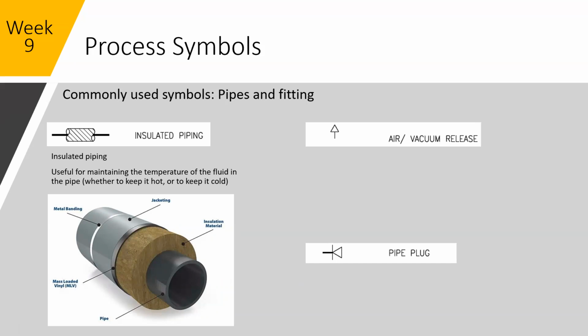You can also get actively heated systems called heat tracing, where you can wrap your pipe in essentially a heat coil. It's like a wire, and then you put insulation around it, and then you run current through it, and it heats up like an electric heating blanket. That's used in water systems all the time to keep the pipes from freezing. People will do that for downspouts and that in their house to keep it from freezing and damaging foundations or weeping systems.